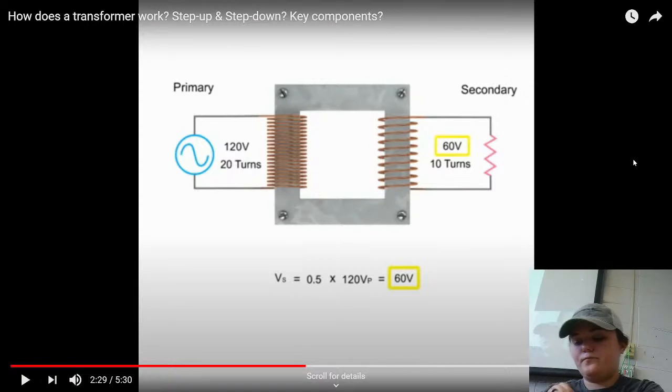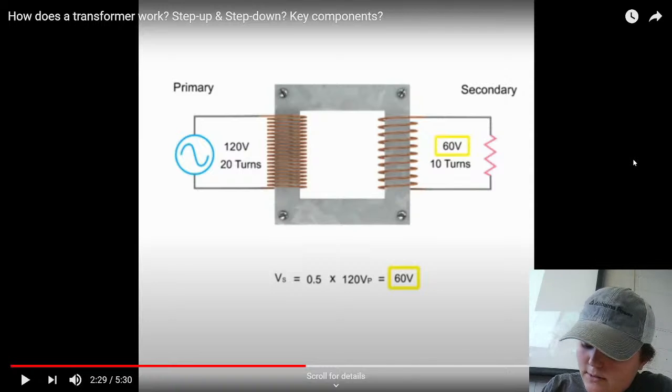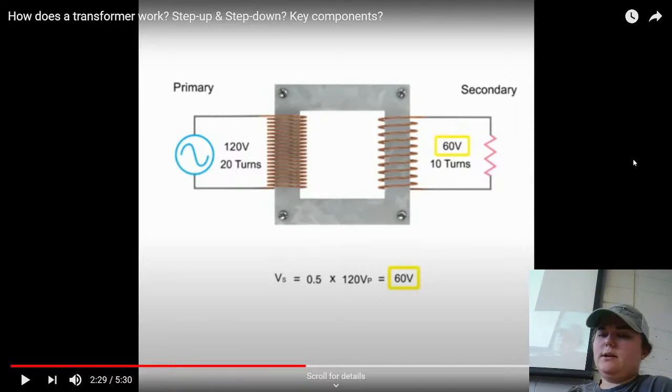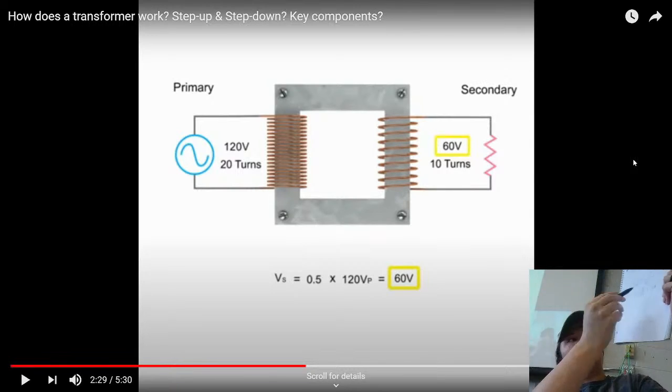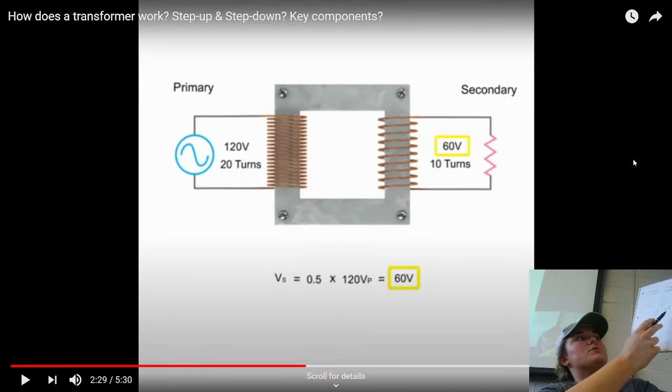All right. So let's see here. All they literally did is they isolated that V. Y'all know how to do math. Well, you're going to bring that 120 volts over and multiply it by that 10 divided by 20. Did you do that step? So it's going to look like this. Can you see that? It's going to be 10 over 20 times 120 volts. And then the easier thing to do is just go ahead and divide 10 by 20, right?